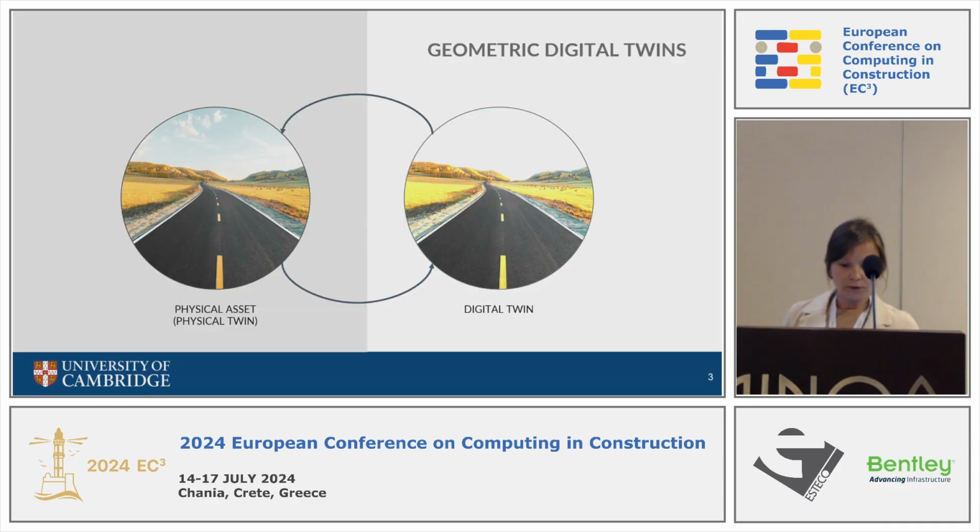Before we move on, let me just revisit the digital twin term. Digital twin here we understand as a digital replica of a physical asset, and it should be part of a twin system where you have a physical asset as a physical twin, and they have a bidirectional connection. So basically, we capture data on our physical twin. We scan it, for example, with LiDAR scanners, with images, with different sensors. We process that data, create our digital twin, so that we can run some algorithms on it, do predictive maintenance, for example, and initiate some actions on physical assets.